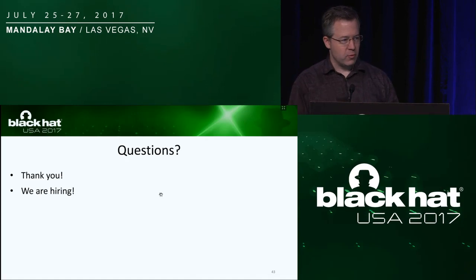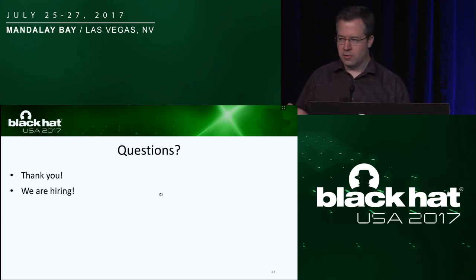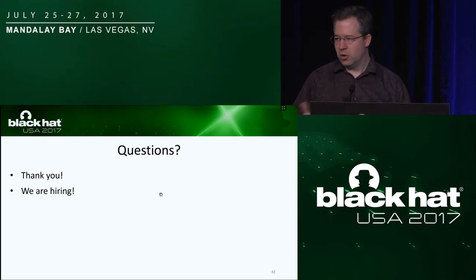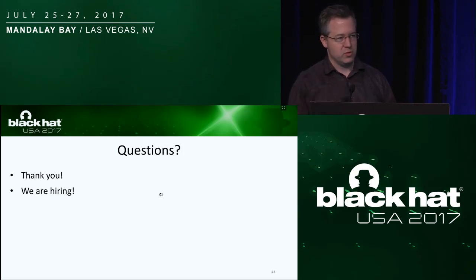So the question was about freezing the RAM to get lower clock speed. That potentially could work. I had mentioned earlier that the lowest clock speed we could achieve while maintaining the JEDEC specification requirement for refresh was 128 megahertz. To lower it than that would violate the JEDEC spec and could potentially risk data corruption. But again, using something like a freeze spray, we could risk going to an arbitrarily low frequency. It's just we're not then guaranteeing that the memory is refreshed at the phase that it requires.